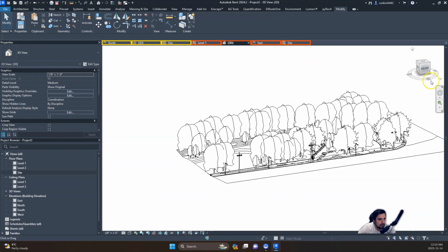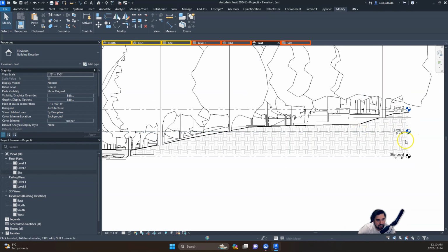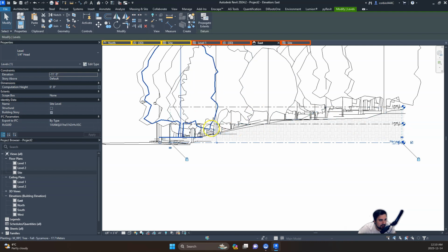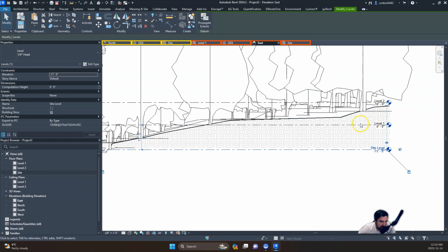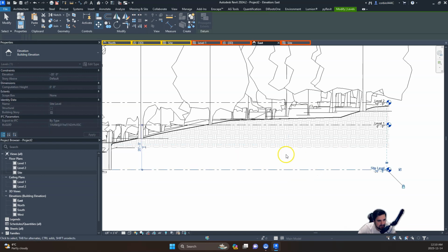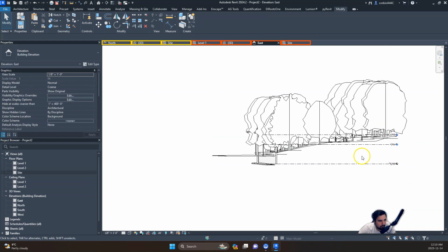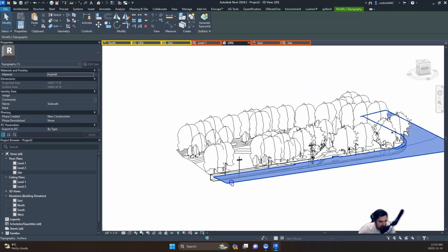So now the next thing just to look at is, right now our level 1 is below ground in this area. And the cool thing about locating this is we can actually have adjustment of our site features now without having to do a lot of work. So I'm actually going to set my site level to be 9 feet down further. So I'm going to set it to be level 20, and this actually kind of worked half as well as I wanted it to.